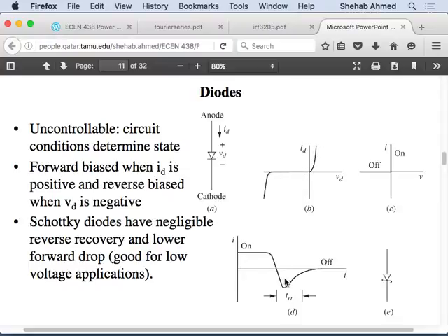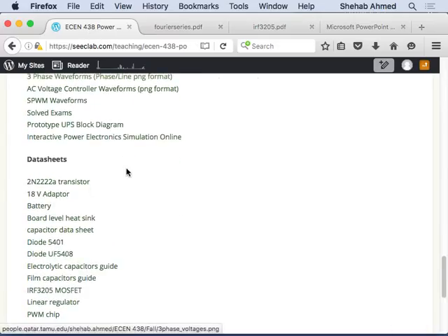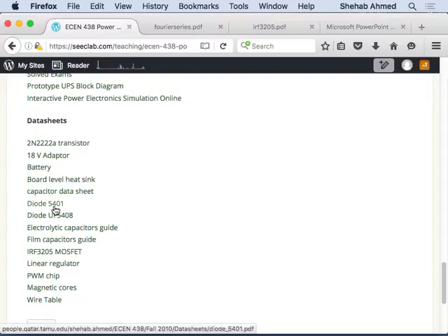This is a dynamic effect that's not actually shown here. This reverse recovery time is a dynamic effect. This is a curve without respect to time. Right. So you went from a device on to a device off. There was some reverse recovery current, and this is something that's in the datasheet of the diodes. I don't know if I have a datasheet of a diode. I do have.